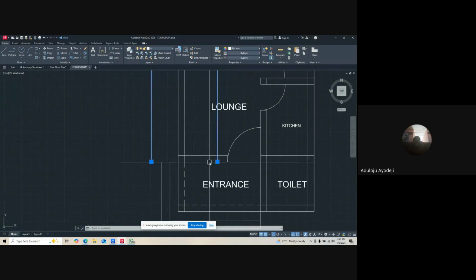All right. So if you want to offset, you offset in the direction you want that thing to go. You can just sit on your AutoCAD interface and think of the offset going to where you want, and you drag your mouse to that place. So now I highlight on it, I delete. And again, the shortcut for delete, you can use E enter. Either you use normal E enter or use normal delete.